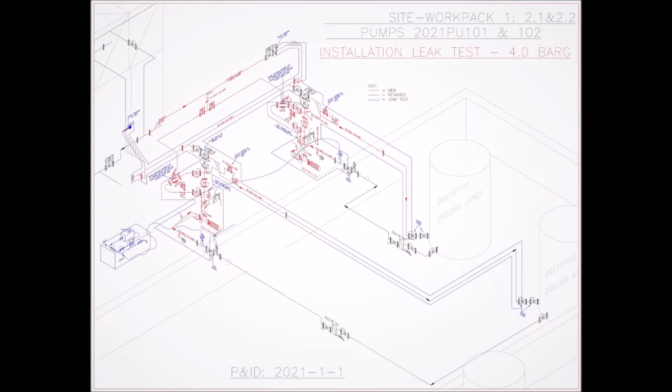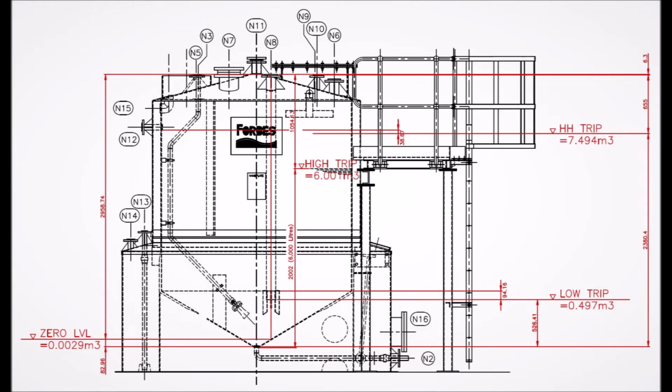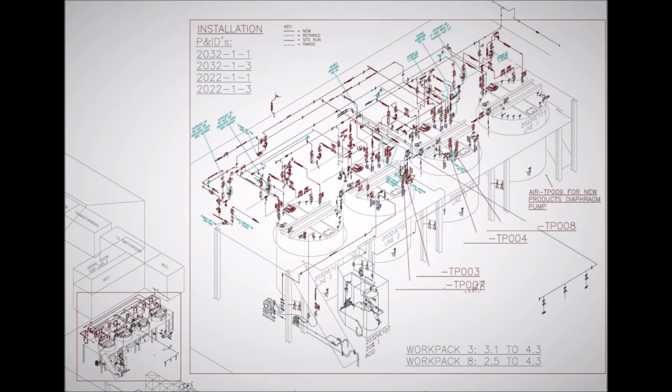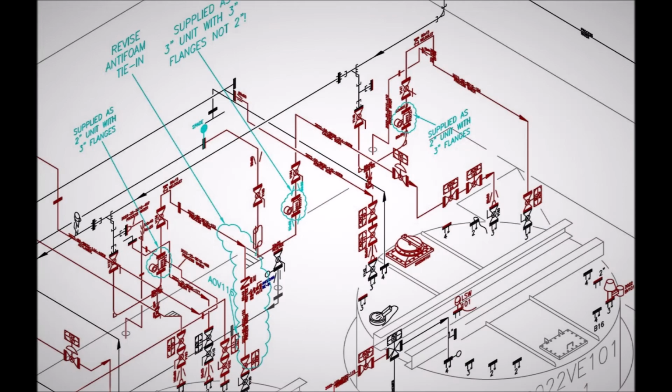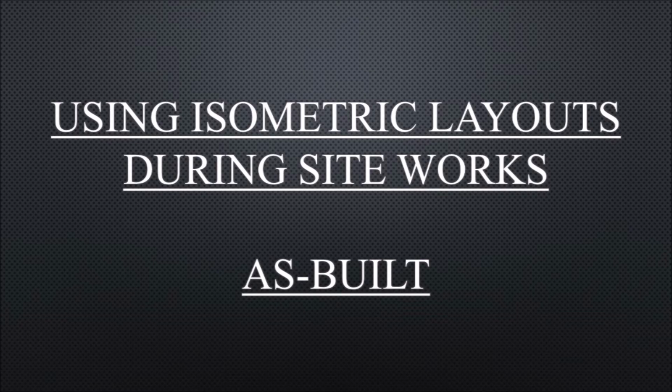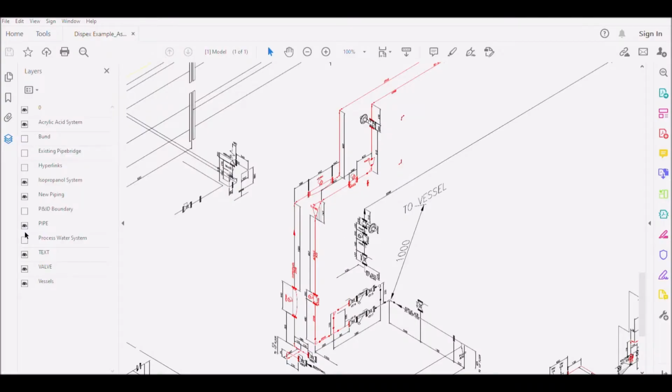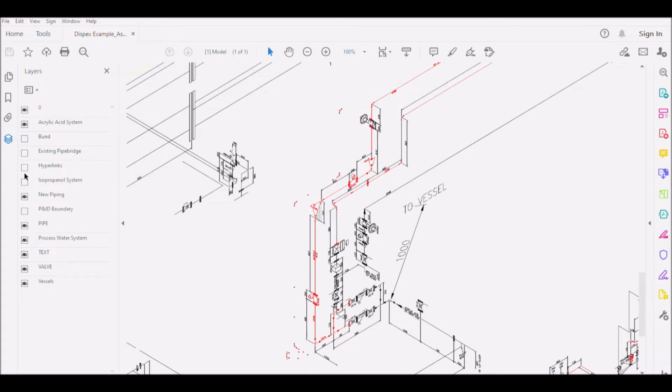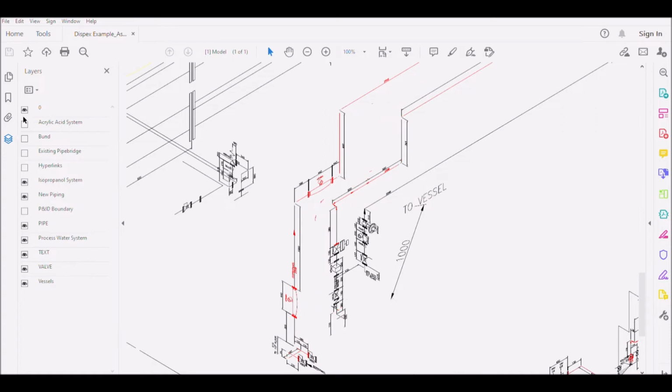Commissioning, including leak test procedure, identifying isolations, high and low points for filling and venting, as well as level sensor calibration checks. Snagging is made easier to track by giving physical locations and description of issues to resolve. As built. All information used during the previous phases can be linked from one common document, resulting in easy use for future reference, be that a HSE audit, system issues or maintenance.